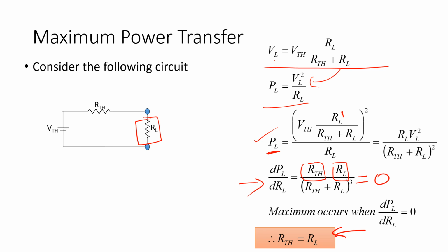Essentially you're looking there at the Thevenin equivalent resistance. So by matching the impedance of the speaker, you could get the most power across. That is the simple thing for maximum power transfer. If you need to find the maximum power that could be transferred to any two terminals in a circuit, you have to find the Thevenin equivalent looking into that circuit, and then the load you attach must be equal to the Thevenin equivalent resistance, and that will give you the maximum amount of power possible.